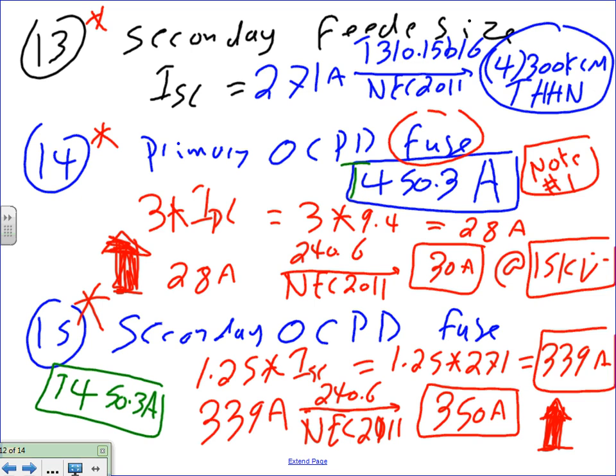My question for Jackson, my friend, can I use 300? Yes. Can I use 200? Yes. If you go lower, what's the advantage of going lower? More protection. What's the disadvantage of going lower? You're taking a chance that the fuses will blow up on inrush when you start the equipment.